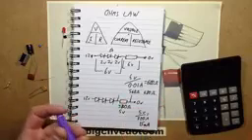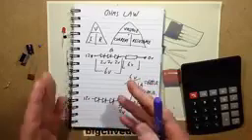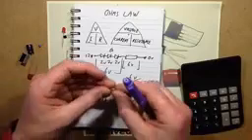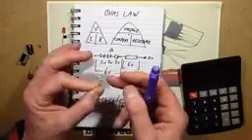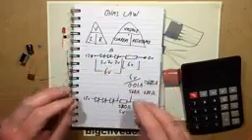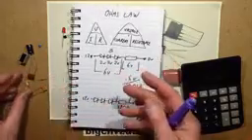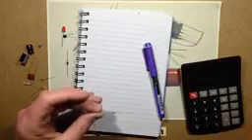Now, resistors, there are a couple of variables with them. You can choose the resistance value, say for instance this is a 1 kilo ohm. And you can also choose the power rating, because if you use too small a resistor, it can actually go up in smoke. Would you like me to demonstrate that? I think you would like me to demonstrate that. Let's use this handily placed 10 ohm resistor I've got here, which is just trying to escape at the moment because it knows what's about to happen to it.